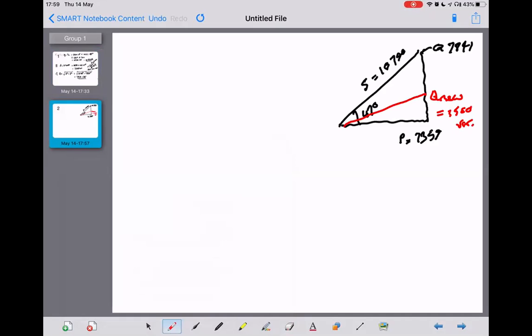And like I always say, it's worthwhile putting a sketch. So we want to know this new angle as well. So we find the new apparent power, S new, if Q new is 1500. Always remembering what happens with P under that kind of situation.